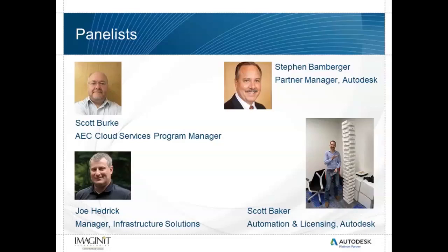Thank you. And Gail wants to know, for BIM360, is full control by the person who set this up in BIM360 and not the team members? I'm assuming full control, meaning you can set up permissions for folders and files within the system so that only certain users have access to certain information. Yeah, you'll designate an administrator for your BIM360 site, and that person will then assign the privileges to everyone else.